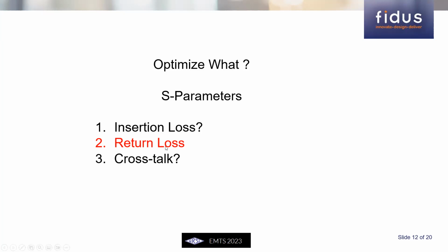Return loss, on the other hand, is significant. Return loss affects the insertion loss deviation. And so it is really critical that you optimize the return loss as best as possible so that the insertion loss is smooth and helps in error-free transmission.